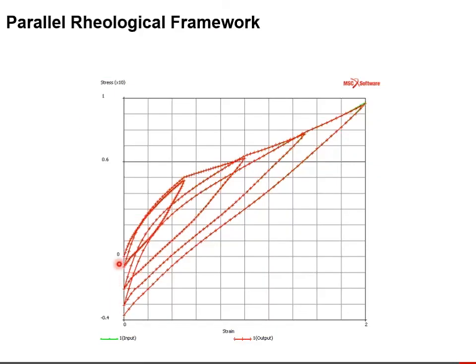So in this example, we can think of this as time. We had one loop here. We unloaded it, went down this curve. We reloaded it here. We unloaded it over there. Reloaded it up here. We unloaded it back there. So you could think of at stress equals 0, the intercept here is really the amount of so-called permanent deformation. And for this particular model, the input or user data and our material curve fit data are really simultaneously on the same curves.